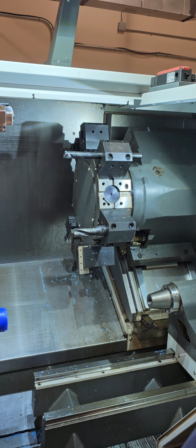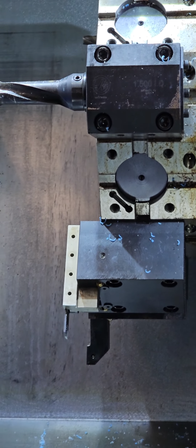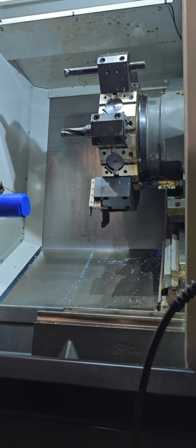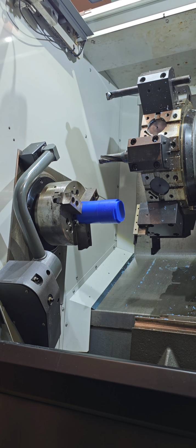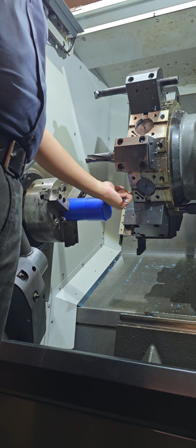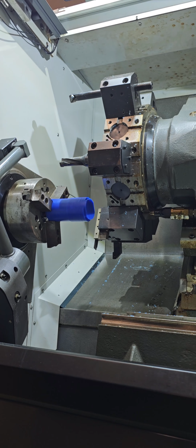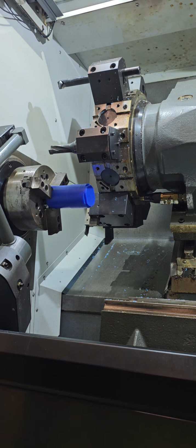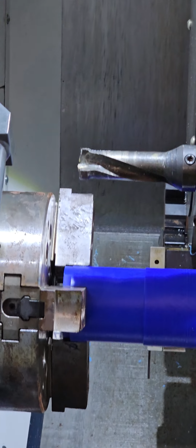All right, so this is a perfect sound. If I have, use your imagination, all right? If you have a tool right here, but you're gonna go ahead and do OD work over here. You have a tool right here and you're working on it. But you're gonna get close, and I'm not even close yet. Probably right there, I'm close. What happened to this tool? I just hit the chuck. It will crash into that chuck. So here we go.